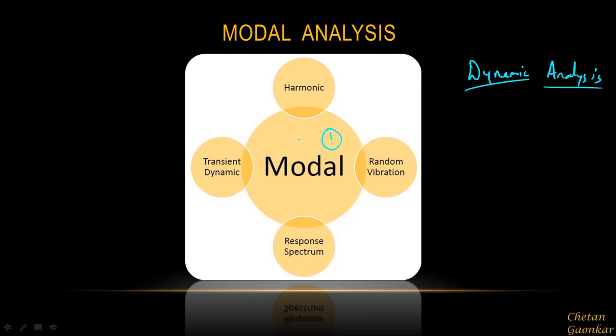Once you perform this modal analysis, once you understand the inherent dynamic characteristics of any system, with the help of that, then you can perform the remaining analysis like harmonic analysis, or say transient analysis, random vibration analysis, and so on. Right, so modal analysis is actually the first step of performing the dynamic analysis.